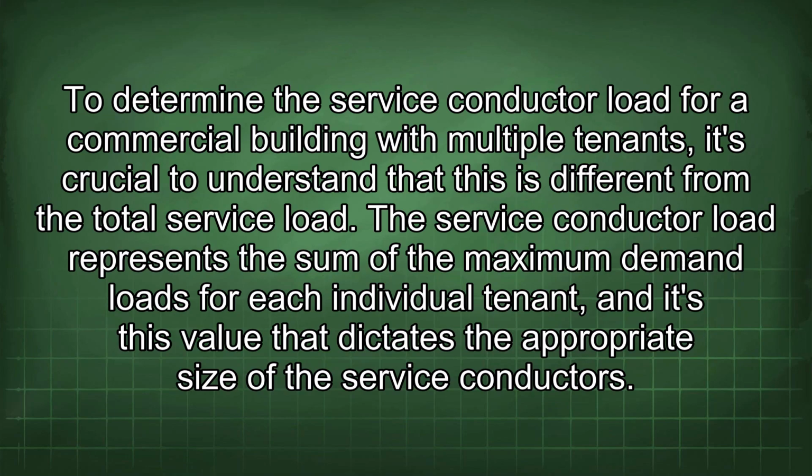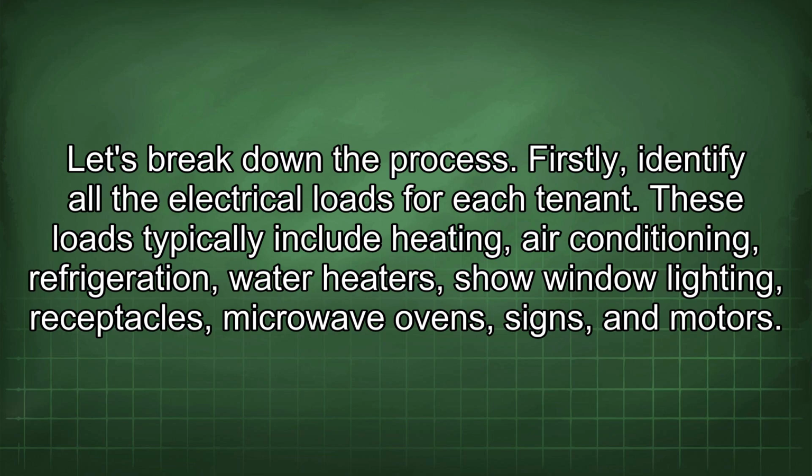To determine the service conductor load for a commercial building with multiple tenants, it's crucial to understand that this is different from the total service load. The service conductor load represents the sum of the maximum demand loads for each individual tenant, and it's this value that dictates the appropriate size of the service conductors. Let's break down the process.